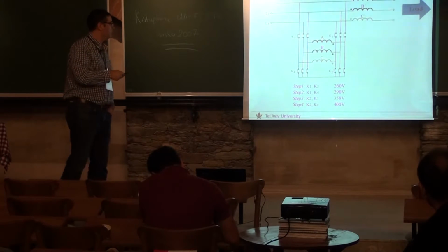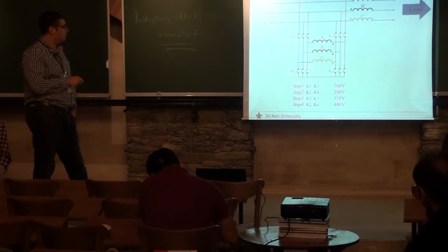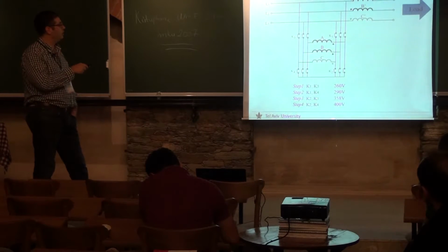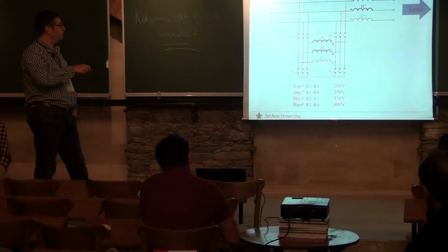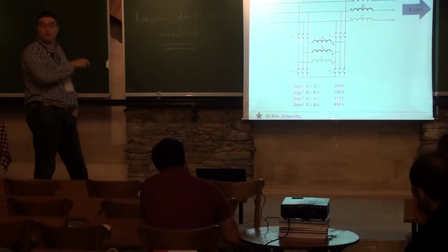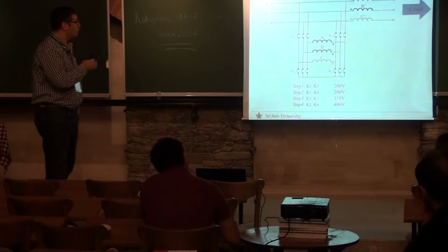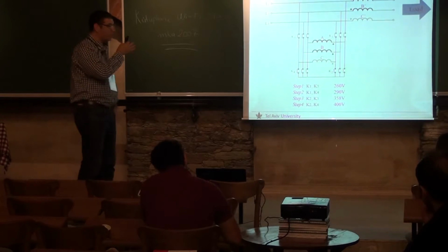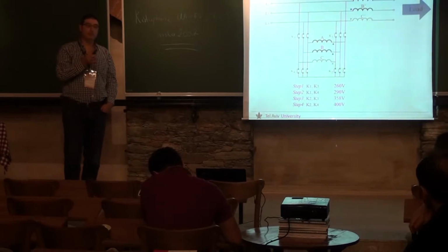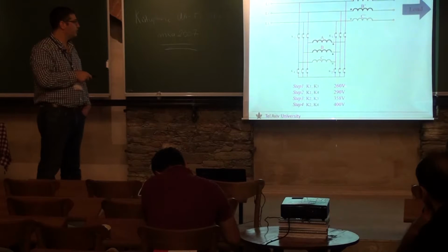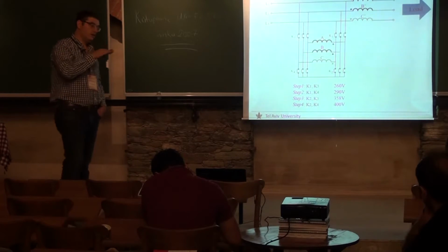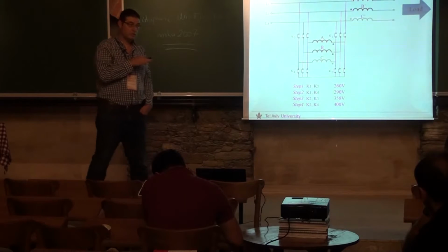And the thing is, we can change the interconnection of the primary. We can feed it different ways. The primary can be connected either in delta or in Y across here, but in addition, we can rotate the angles depending on which primary phase we connect to each line. Altogether, it seems like a lot of options, and there are a lot of options, but they overlap. So eventually, what we are able to do is generate three voltage reduction steps.